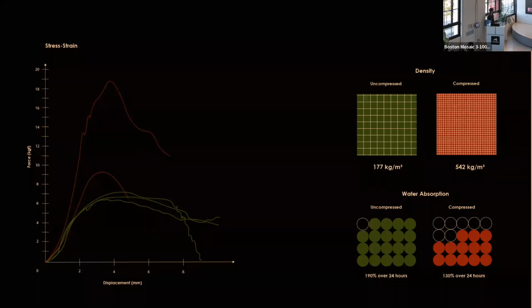The red lines are the mycelium sheets. For one of them, the adhesive came off, so it didn't work really well. The other one that you can see higher up is where one of the mycelium sheets' strength came out, at around 1 megapascal of compressive strength. The sheets had relatively lower strengths. I would expect the actual strength of the sheets to be 2 or 3 times higher than this, and that would be really interesting, to have high performance materials like that.